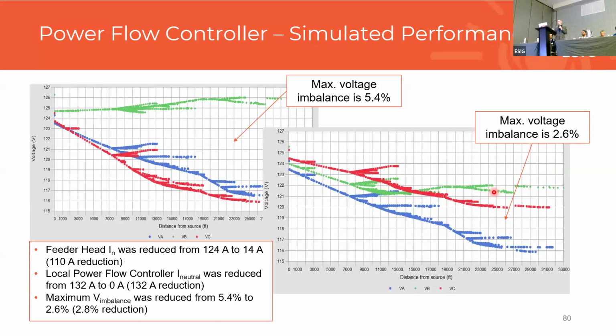And then in this case, we can see that before the device, actually both A and C phase were pretty close to being at a limit. They were both at about 95%. After you added the device, it really helped your most heavily loaded phase condition. It pulled a lot of power off of one of the phases. It looks like C phase in this case. It was likely heavier loaded. So it pulled a lot of power off of C phase and it dumped it all on B phase to correct for the imbalance in the system.